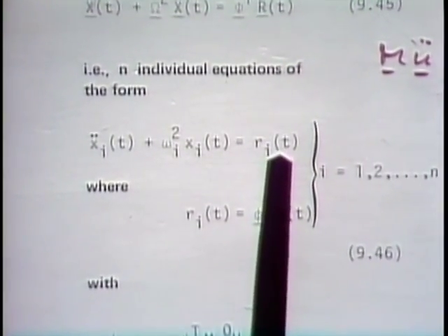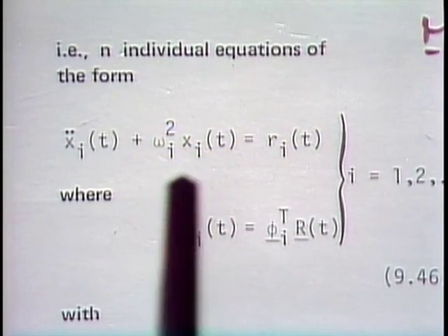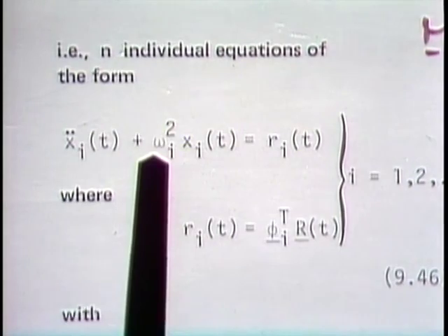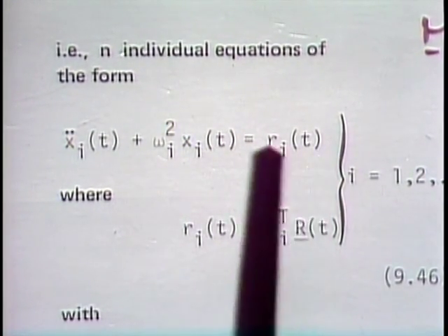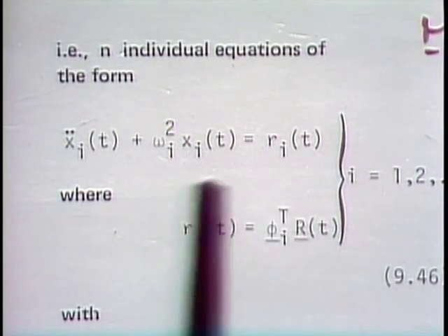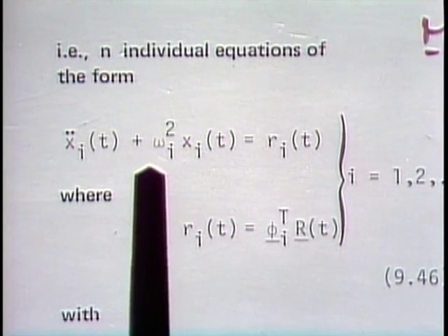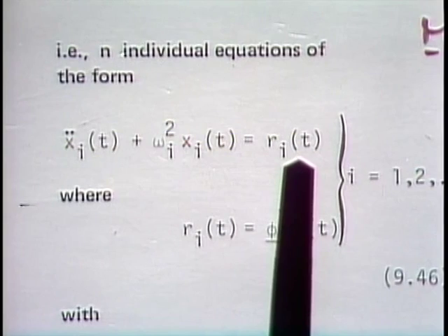Well, and this is what we are using in mode superposition analysis. We only need to consider those frequencies of the system, the omega i's, which are truly excited by the dynamic loads. We only need to look at those decoupled equilibrium equations for which the frequencies in the decoupled equations are truly excited by the dynamic loads.